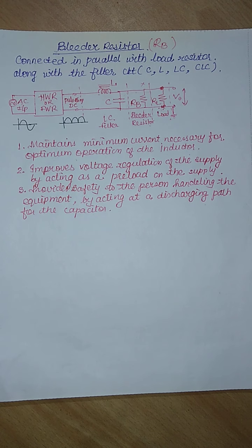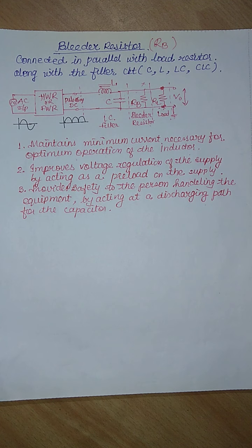Then it improves the voltage regulation of the supply by acting as a preload to the supply. And third, it provides safety to the person who is handling the equipment by acting as a discharging path to the capacitor.